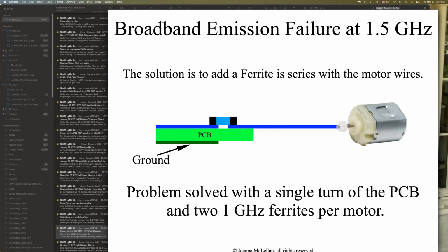You're changing the resonance structure. Is the capacitor at the motor going to work, or will the capacitance at the motor cause a different loop that'll have a different area, which will have a different emission? Right, you'll probably end up with a higher Q, different resonant frequency, right? If you have a capacitor that's just contributing to a higher Q resonator tank. The other issue you have is that at 1.5 gigahertz, if you want it to be a capacitor, not an inductor, you're pretty much going to have to use a small surface mount part, which I'm not sure you could get on the leads.